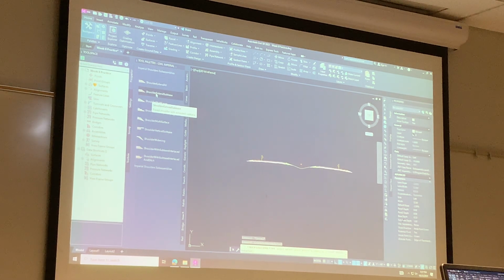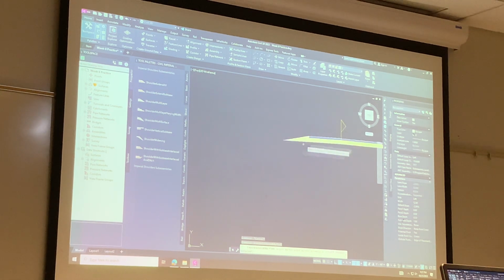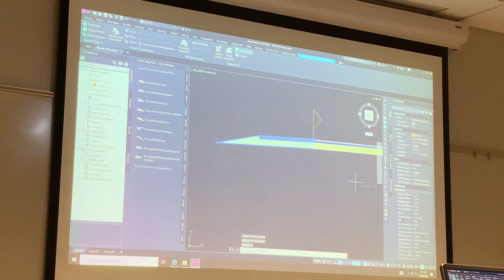The right shoulders, the shoulder extended something. Okay, yeah, so I changed the width to 10, so a shoulder width to 10 feet, and I changed the default shoulder slope to -5%, and I changed the default sub-base slope to -5%.